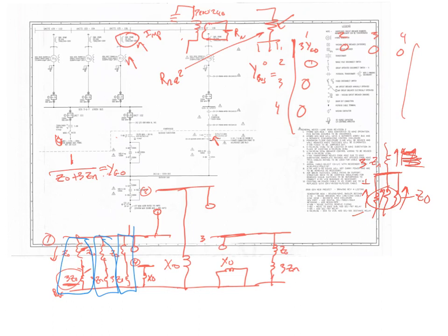The ground. It's always the gotcha. Ground is the most difficult one to coordinate. The event I told you about in 2014 or 2015 at Millstone, which tripped off a nuclear power plant facility and ended up causing an unusual event, was a result of an uncoordinated ground system. So, for what it's worth.